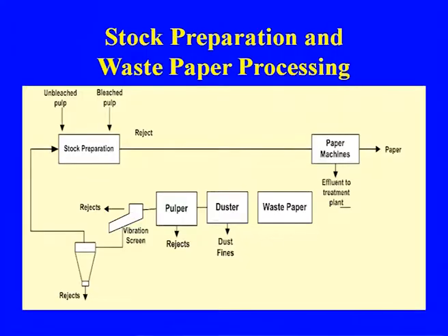So, even coating is also done. The coating part is finally done after the making of the paper. The bleached pulp going to stock preparation goes to centri-cleaning, where the rejects will be removed, and then finally the pulp will go to the machine, and the waste water will go to the effluent treatment plant, and then the final paper will go to cutting, reeling, and all those processes.